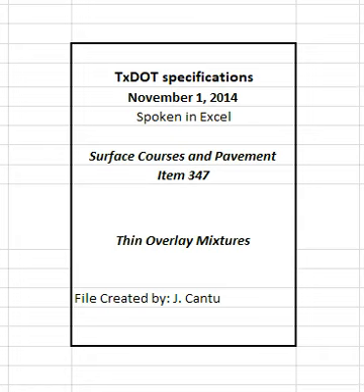4.9.2.4.1 Gradation. Suspend operation and take corrective action if any aggregate is retained on the maximum sieve size shown in Table 6. A sublot is defined as out of tolerance if either the engineer's or the contractor's test results are out of operational tolerance. Suspend production when test results for gradation exceed the operational tolerances for 3 consecutive sublots on the same sieve or 4 consecutive sublots on any sieve unless otherwise directed. The consecutive sublots may be from more than one lot.